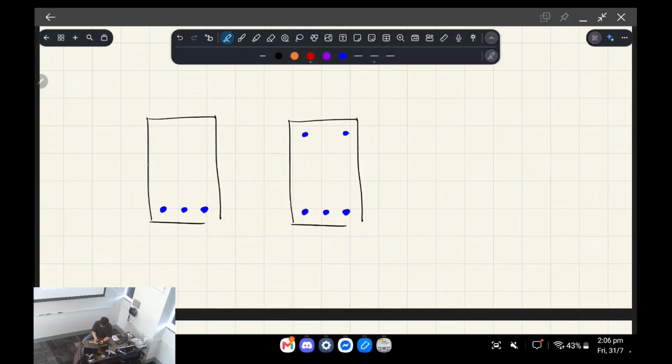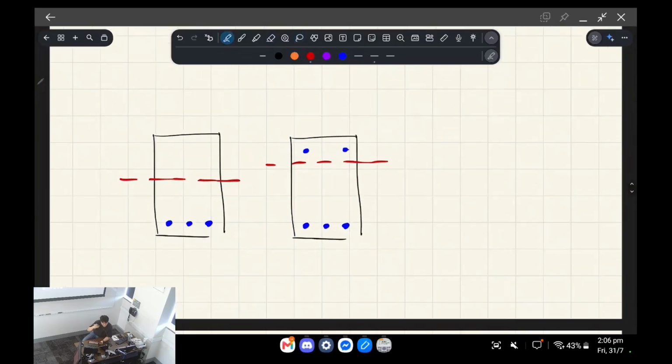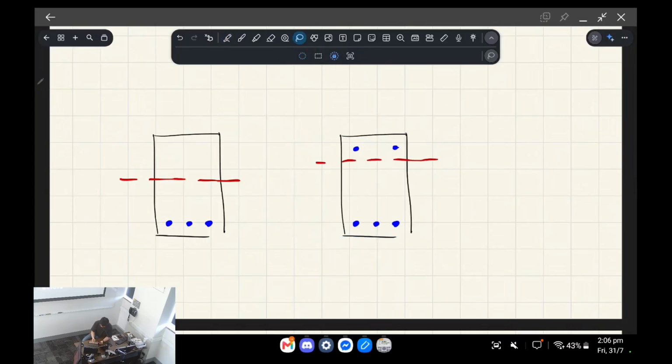Your neutral axis will be brought up if you have compressive reinforcement. That's for one, okay? I'm going to exaggerate it a little bit, but it brings up your neutral axis. What this is going to do is, when you're doing force equilibrium, like so, it's also going to add... anyway, so that's your strain, let's say.